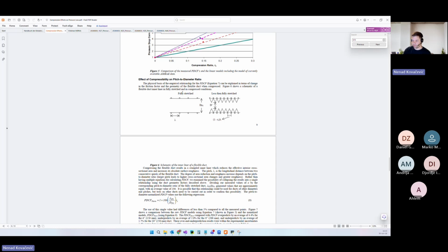That flexible duct is usually supposed to be 1 or 1.1 meter, but it's 3 meter, and then you reduce basically the diameter for the flow. With that, you increase the velocity. So actually the pressure drop in the flexible duct will be 4 to 10 times bigger than what you're calculating with ideal conditions.